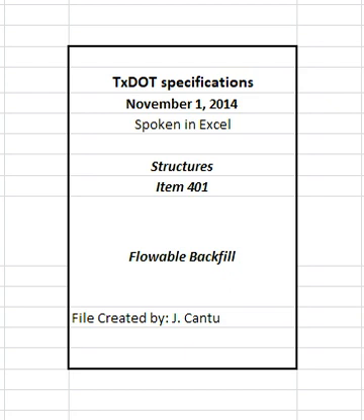2.4 Fine aggregate. Provide fine aggregate that will stay in suspension in the mortar to the extent required for proper flow and that meets the gradation requirements of Table 1. Table 1. Aggregate gradation chart. Sieve size and percent passing. Sieve size 3/4 inches with 100% passing. Sieve size number 200 with 0 to 30% passing.